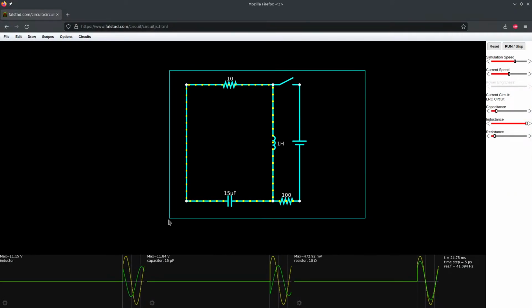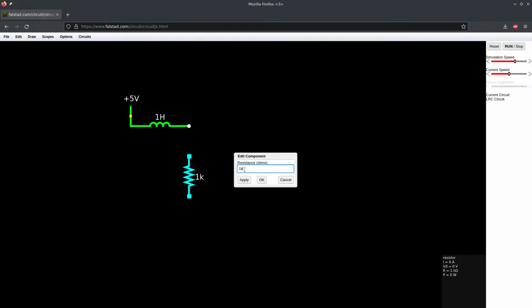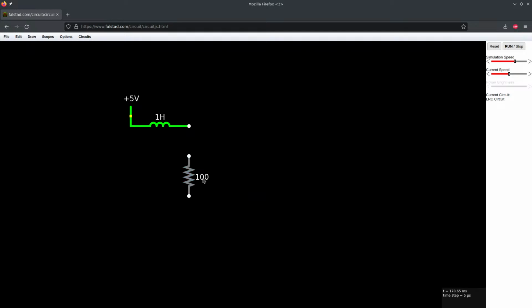So let's see here. Really quickly, I'm just going to put a voltage source here. So the reality is that connections aren't perfect. They have some inductance to them. And I'm going to put this resistor right here as the load for our microcontroller. If we look at the voltage that we get across this as we connect, every time there's a clock on the microcontroller, it's sort of doing the equivalent of opening and closing a switch. There's a little gulp of power it needs every time.